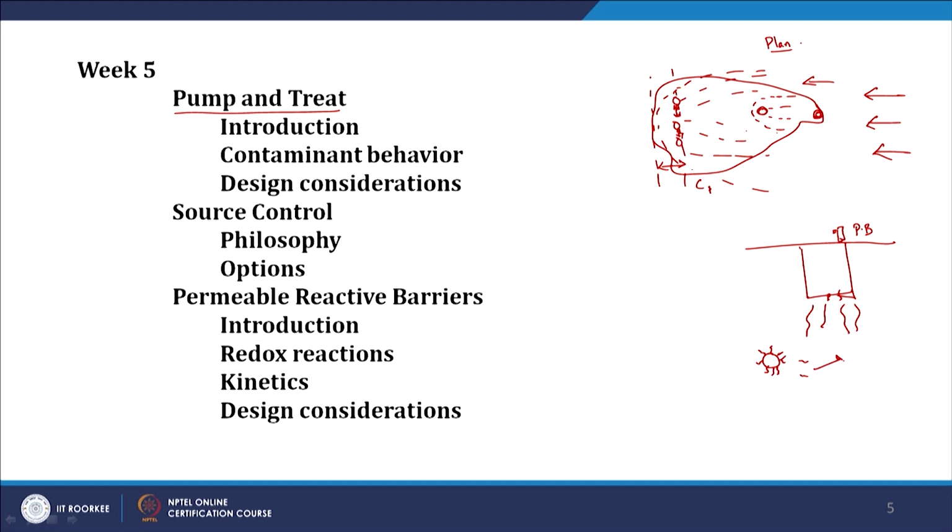If I keep trying to pump out this groundwater, there are going to be considerable issues that come into play, such as tailing and rebound, and again the time required for pumping out the relevant contaminant, because there is going to be desorption from the soil, as the compound is preferentially adsorbed onto the soil.